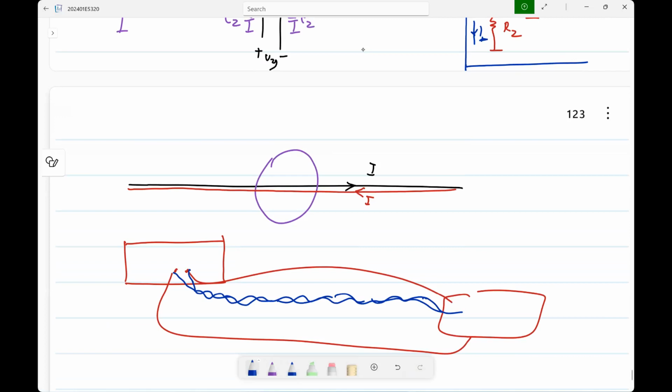If the rate of change of magnetic flux cutting the loop is small, then you neglect that and you make it equal to 0. But if you have a huge loop and then you have that integral of dB by dt, in the differential form, if the integral of this is not negligible, actually the sum of voltages is not 0. This is how it is useful in a generator: you have a changing magnetic field and it induces a voltage. But when you are making a circuit and you want the voltage here to appear there, you don't want that to form a big loop, because then the voltage that appears here will be the voltage that you apply here plus whatever is the result of changing magnetic field. So you should keep the loop area as small as possible.